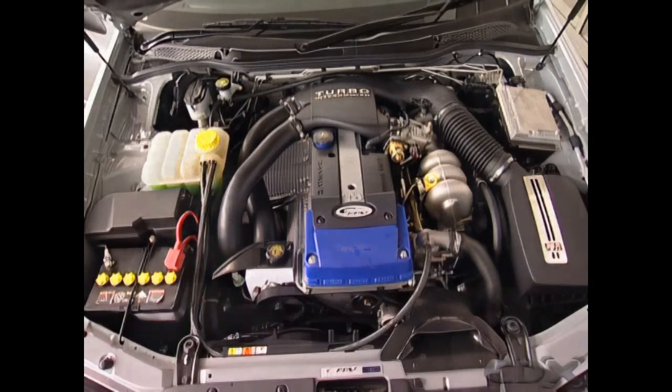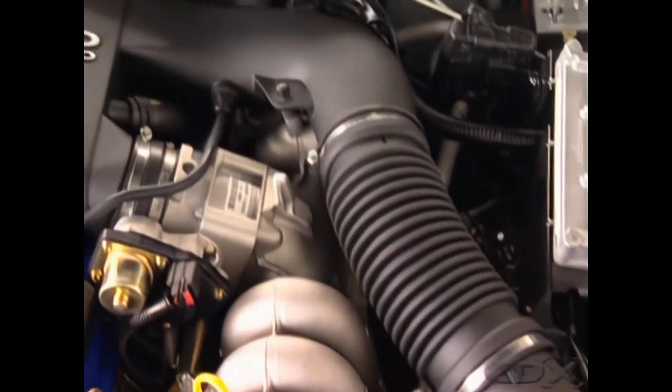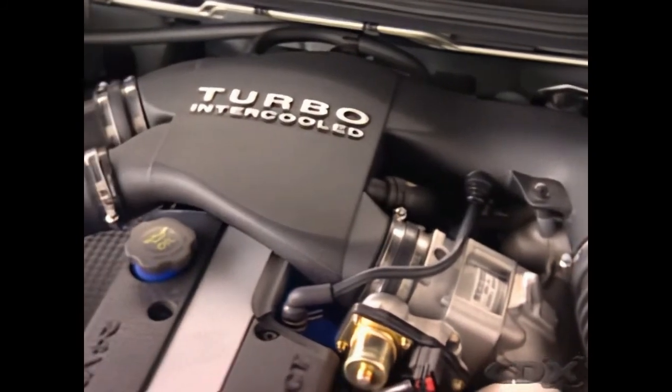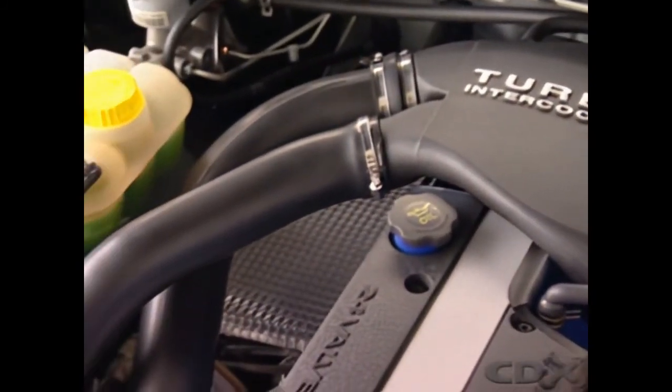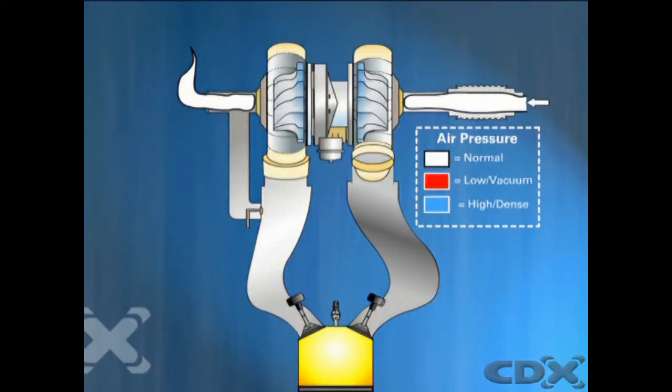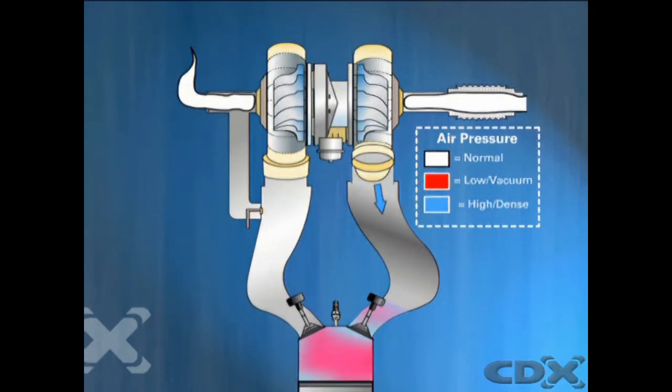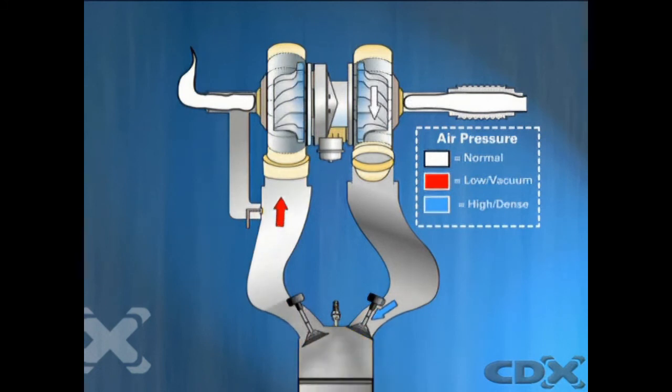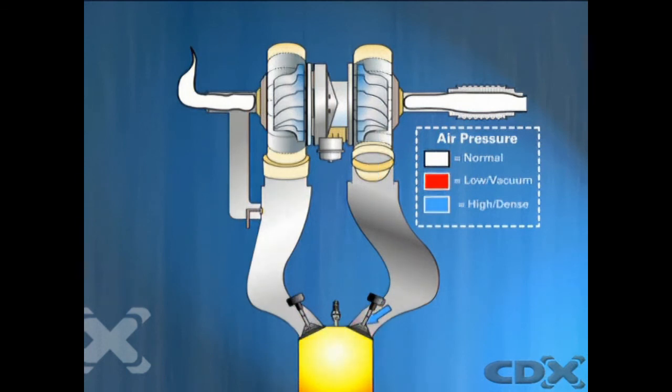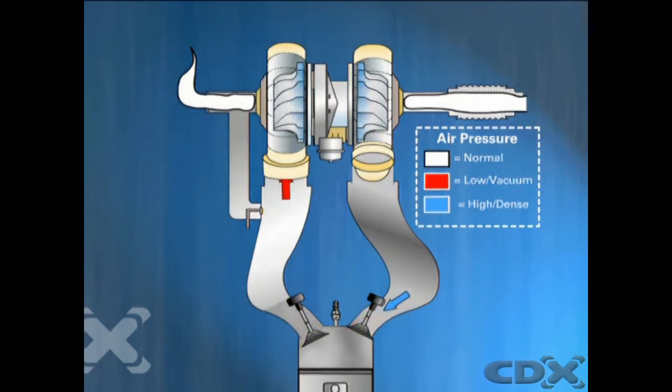A turbocharger is a forced induction system that uses wasted kinetic energy from the exhaust gases to increase the intake pressure. Like superchargers, turbochargers increase the amount of air that flows into the engine, but they have a negative effect on the flow of air out of the engine. This means that for maximum power output, valves, cam timing and exhaust system design are more important in turbocharged systems than in supercharged systems.